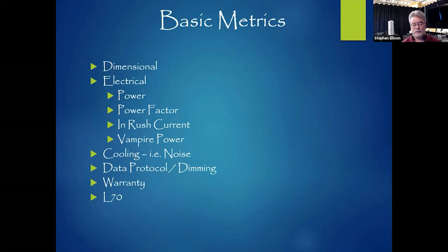So the manufacturer should be telling you exactly how many fixtures you can put on a breaker or a circuit. Something that makes a difference, because you'll say, well, it's 100 watts each, because you didn't have inrush current as any factor in a dimmer system. An incandescent lamp, you turn it on, it's 100 watts, you're drawing 100 watts from the beginning, or as you dim it up, you go from 0 to 100 watts.